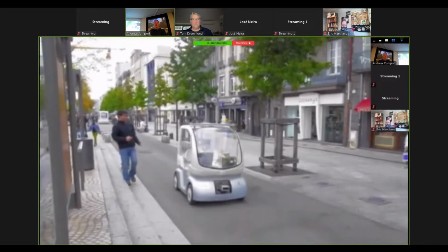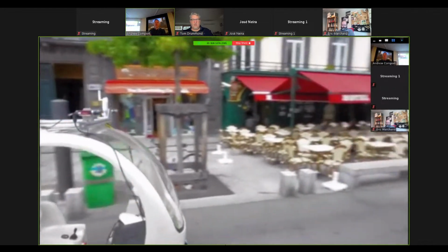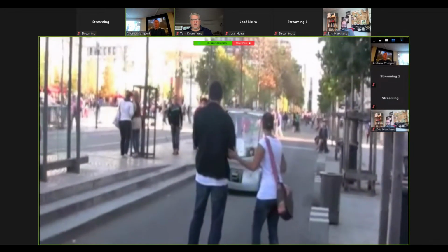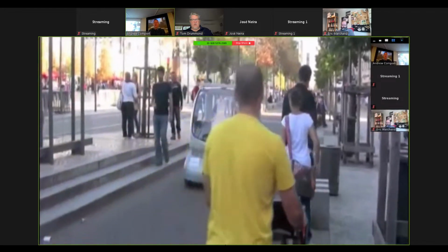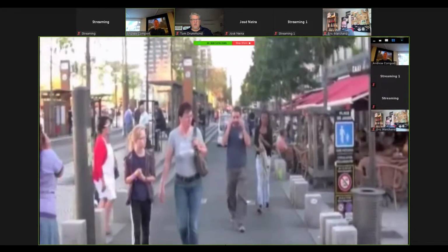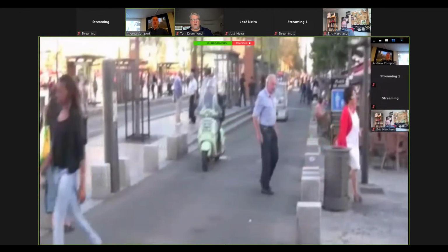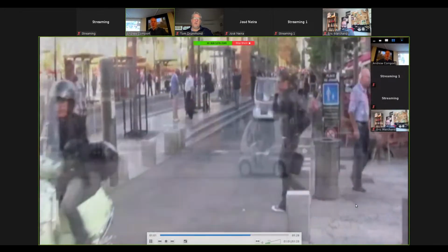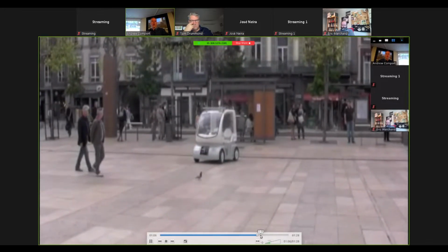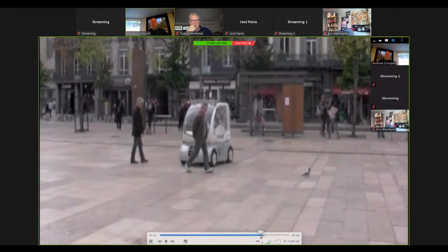This was before all the autonomous cars started coming out, such as Tesla. We have a laser sensor just for security, so mainly it's vision only. It's just a laser sensor to make sure that if an obstacle walks in front, the car will stop. You can see here it's able to handle lots of noise and outliers with respect to the map and locate the vehicle and send the control back to the vehicle to follow the path that was planned. Here you can see the obstacle detection running as a bystander walked in front.